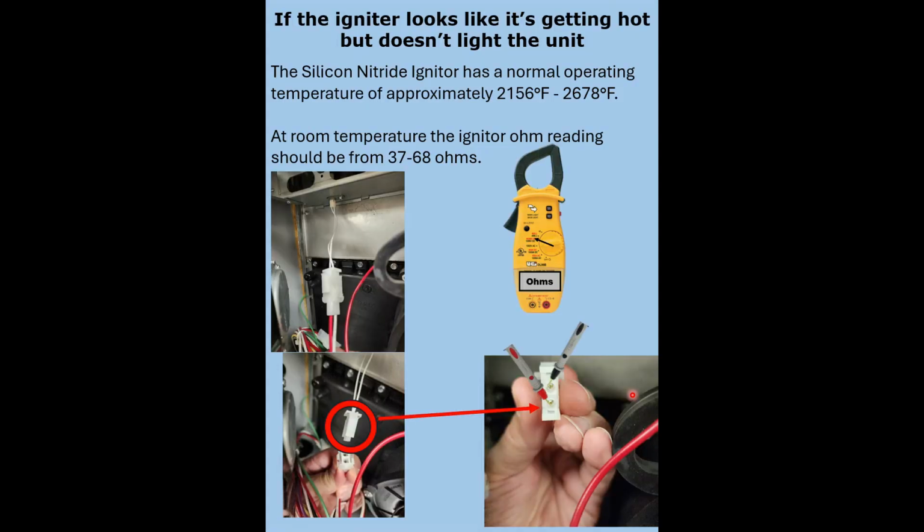And here we see that you break this open. You see the igniter right up here in the left-hand corner, and this plug comes down from it. We break this open, as you see here. Then we take the igniter side and we ohm it out with our probes here. We could also see if there's voltage there, do a voltage test after or whatever. But right now we're ohming out the igniter, but you could use this to do a voltage test on it also, run it through another cycle.